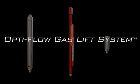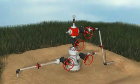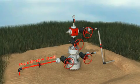The OptiFlow Gas Lift system by PCS uses a high-pressure source at the surface to inject gas down the annulus into the tubing. The compressed gas is injected into the production stream through gas lift valves fitted in integral mandrels. The mandrels are installed as part of the tubing string and are positioned at prescribed depths.